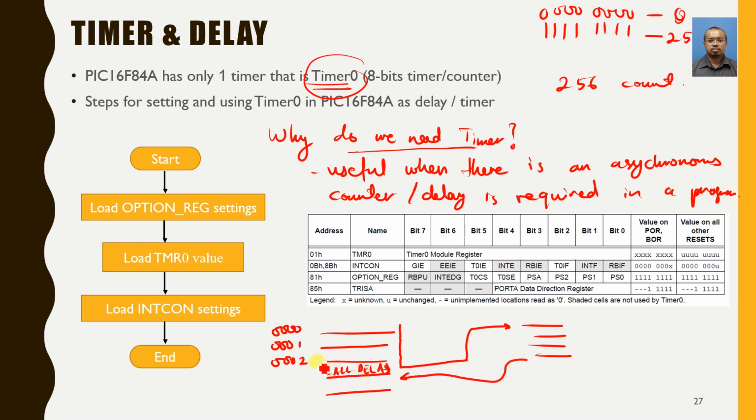So the program counter will stop from 003 here. It will serve this delay subroutine, and then it will come back, and only then will it continue with line number 4, which means between 3 and 4, the program was stopped to do the subroutine to perform a delay.